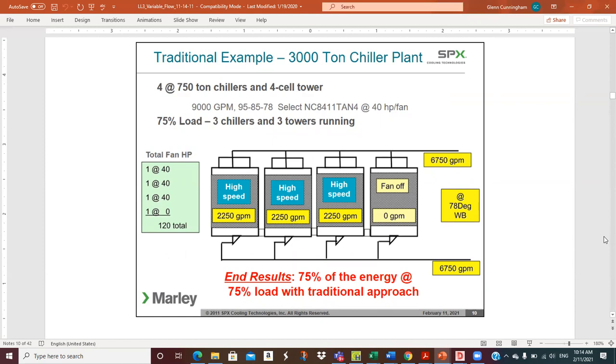And you know what? If you've got a chilled water plant set up like that, for the vast, vast majority of the whole cooling season, you don't need all 4 chillers. It's really, really hot maybe a lot of July and August, but you get into September, October, November, December, heavens no, your load falls because it's not hot outside. So this is pretty compelling.